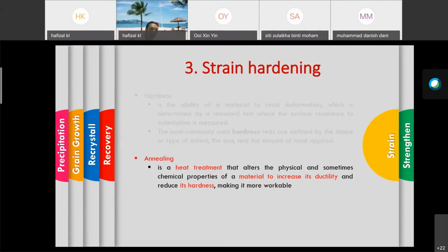So during the process, macam kita buat forging, macam buat keris, buat pedang, buat pisau, apa semua tu. So it depends on the material. If the material is physically hard, we cannot forge it at room temperature. We need to introduce heat at a certain temperature, and then it will allow us to make a deformation.